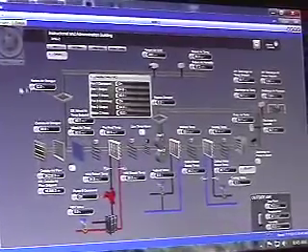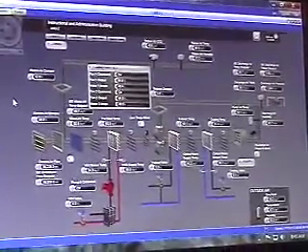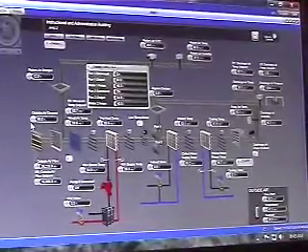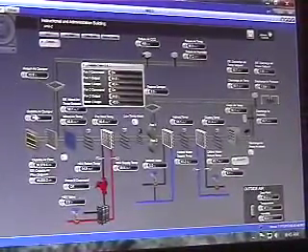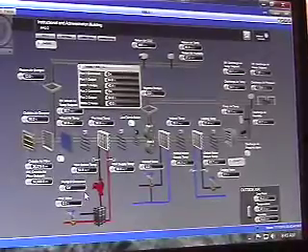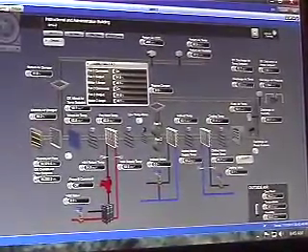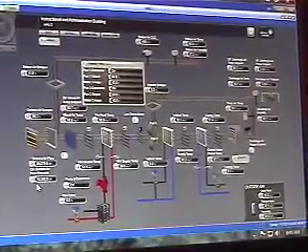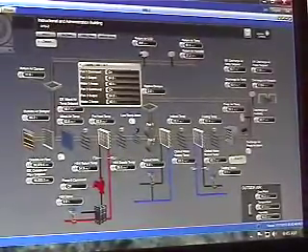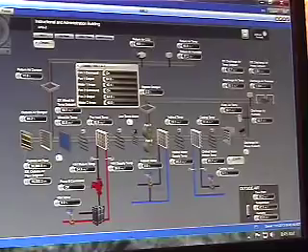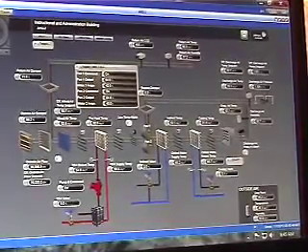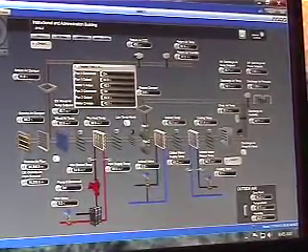Coming down, return air damper here, outside air damper here. 2 separate signals, but they run together, just inversely. So as this one's 12%, this one's 88%. They just work opposite of each other. Here you have your outside air flow reading, and your set point. That set point, as I mentioned, will reset based off of CO2 position. Otherwise, it just has a fixed minimum outside airflow set point.